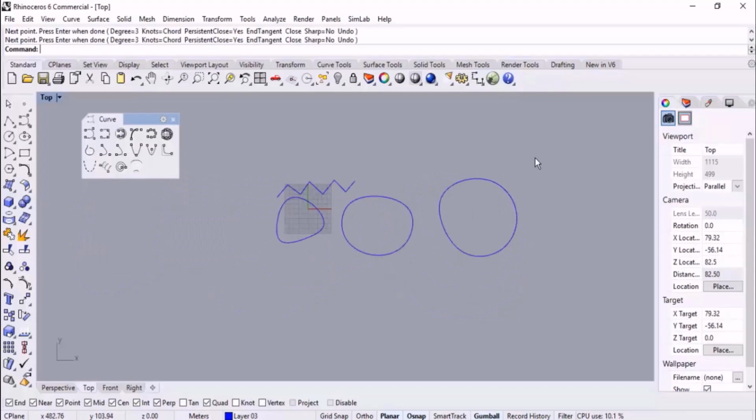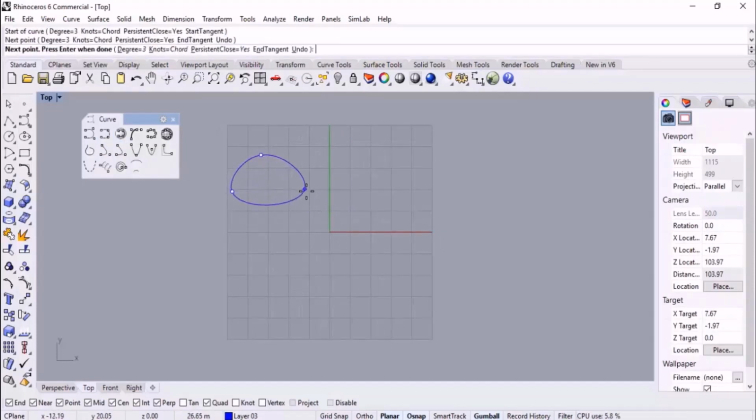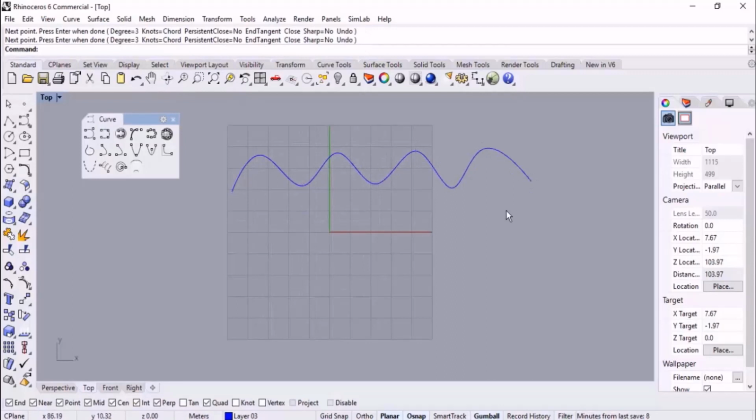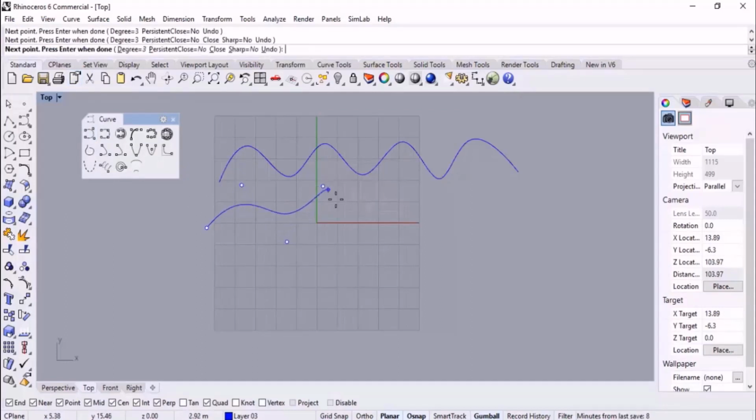Well done. But about the points that you should take into consideration, as I told you before, sketching curves like interpolate curves is a much better option because you get better control over it, since the points got interpolation into the line, so you can control them better. To compare with the control point curve, I set the degree to 3. Let's check it out. The control point curve.